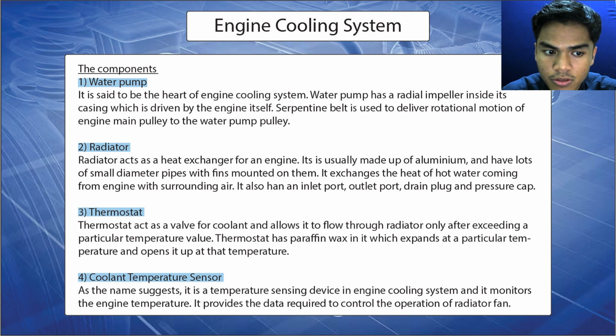Number two component, radiator. The radiator acts as a heat exchanger for an engine. It is usually made of aluminum and has lots of smaller diameter pipes with fins mounted on them. It exchanges the heat of hot water coming from the engine with the surrounding air.